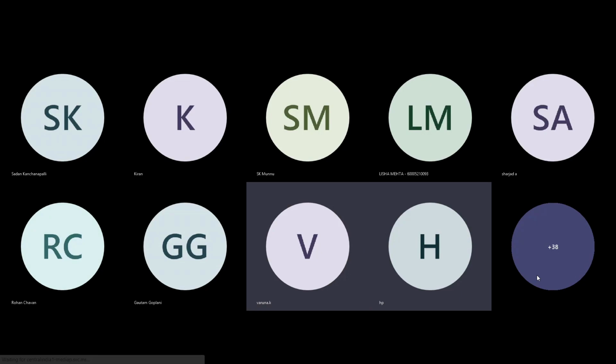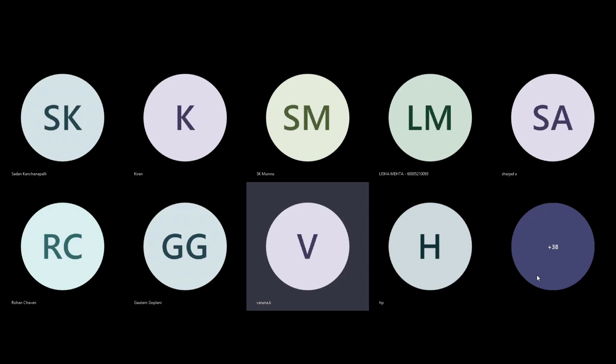Yeah, these three. CFD. Okay, after that FEA for the static analysis. Then for the vibrational analysis, you need to go for the dynamic analysis. That is random vibration and the harmonic and the modal analysis. These three come under the dynamic part of it. And whatever I have shown you, that is static analysis.